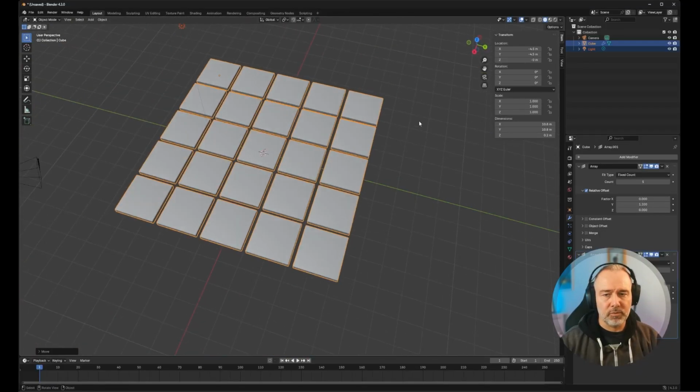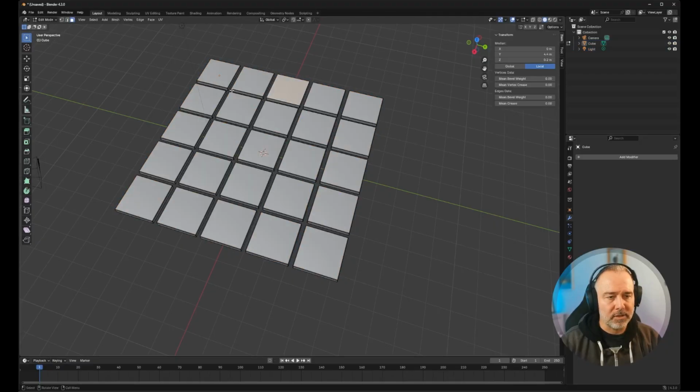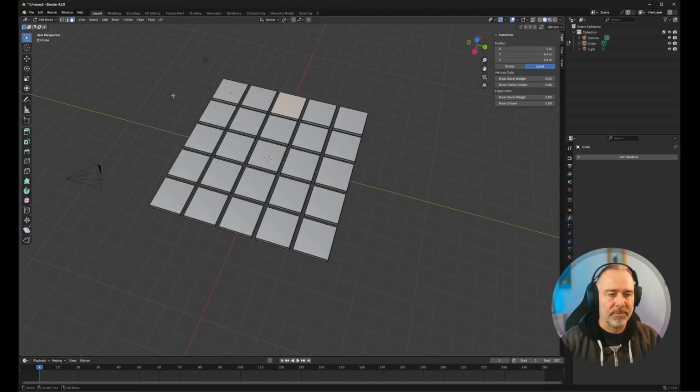Now, this is just one object which is called cube001. First thing first, I want to apply these modifiers. Right now you see I have full control, I can tweak it, but I cannot really play with the geometry. I'm going to go here, and you have Apply, and I'm going to apply this one. Now I can enter in, and you see I can select the faces, etc.